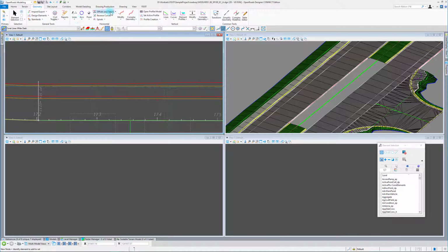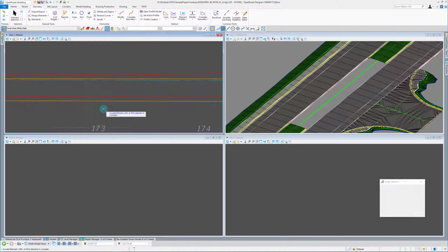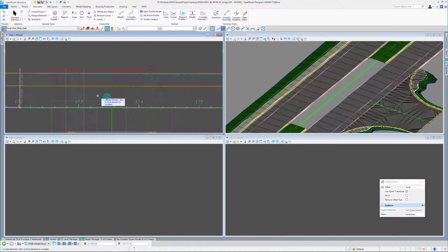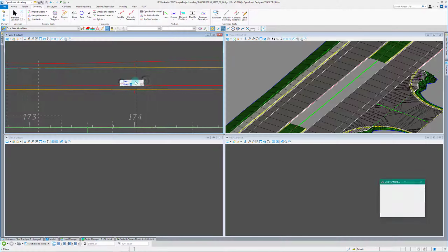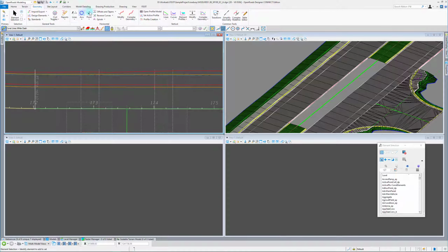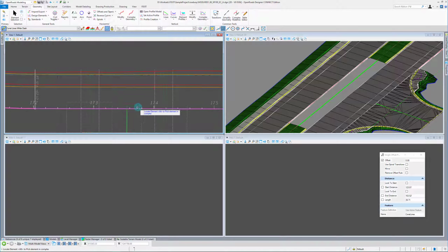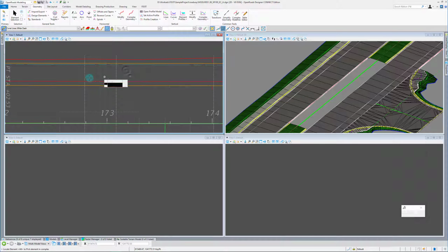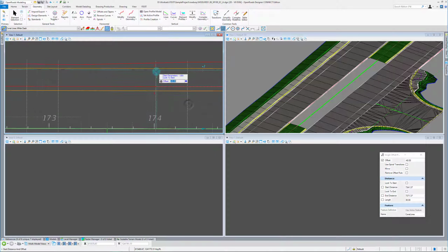So what I'm going to do first is you know how I like to create some boundary elements for things I'm going to model. So I'm going to create some boundary elements off of this crosswalk to kind of get my modeling going here. So just going to do 10 feet on either side. So I'm going to set up my edge of pavement, 40 feet offset. I'm just going to snap it to my boundary elements for both of my crosswalks.